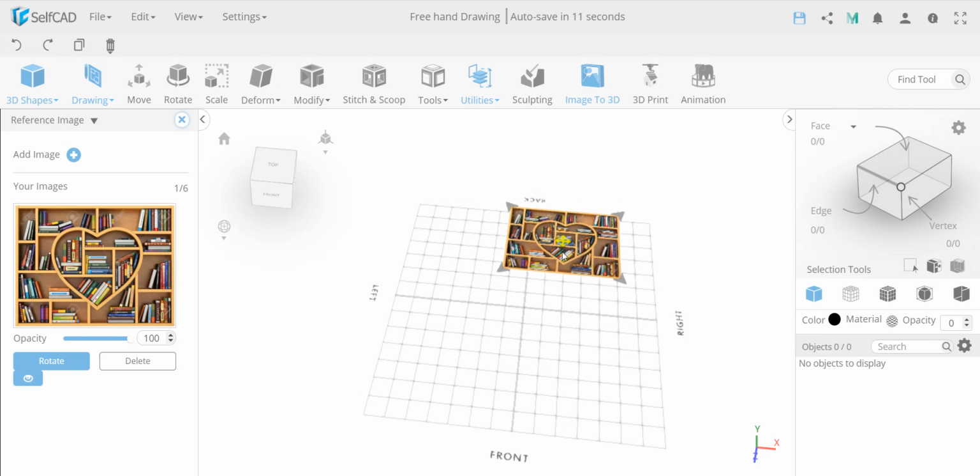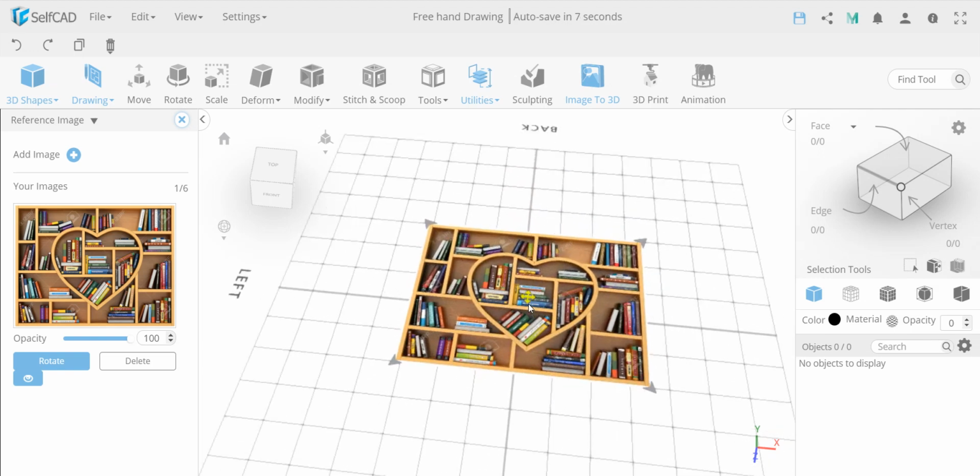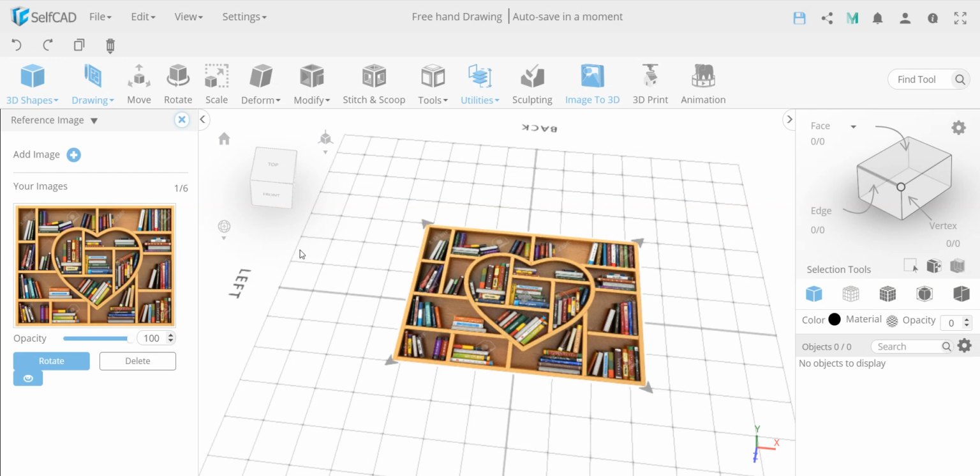And before I center it, I want to show you another trick, because when you're going to trace something, you want to have real measurements. It's a general practice in most 3D applications. Also, I just want to note that this idea of reference images may be called by different names, but it's standard practice in any standard CAD package. So before we make this perfect, if you want to measure something in sizes, let's say I want to know how big everything is, I need to put it in proportion. So I'm going to first make it a little bit opaque. I'm going to put in a 25.